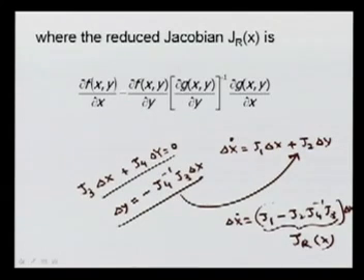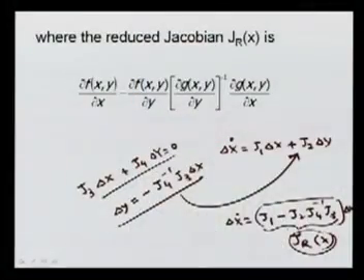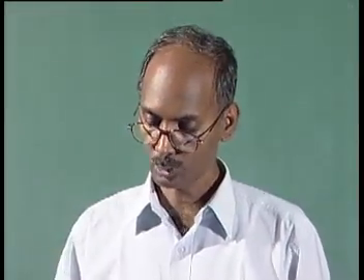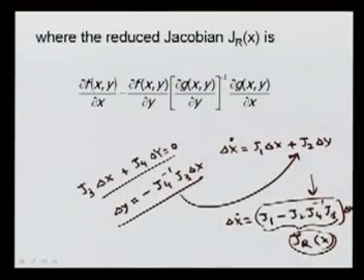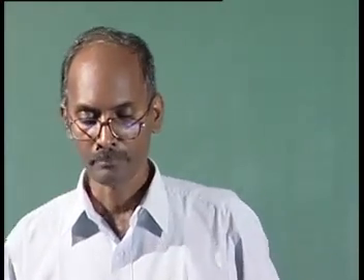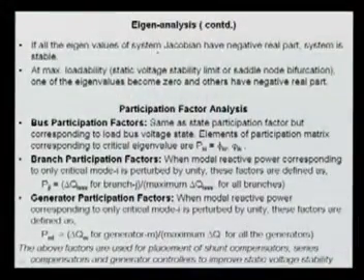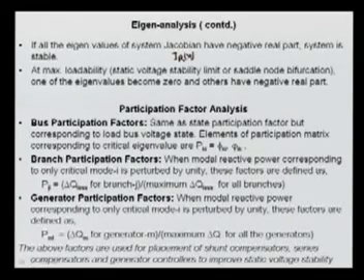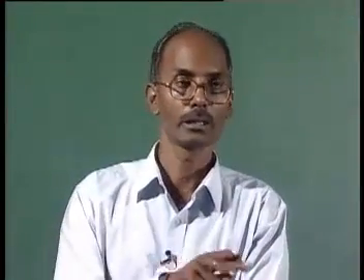Now this matrix gives information like a steady state power flow Jacobian, and we can analyze this matrix to get information about the condition number and other things, and the system stability conditions. Here we can analyze using the eigenvalues of this matrix, and based on that we can conclude several things. This J_R is not the power flow Jacobian, it is different, because the power flow Jacobian is included in it, and in that case we have used the dynamics of the system along with it.